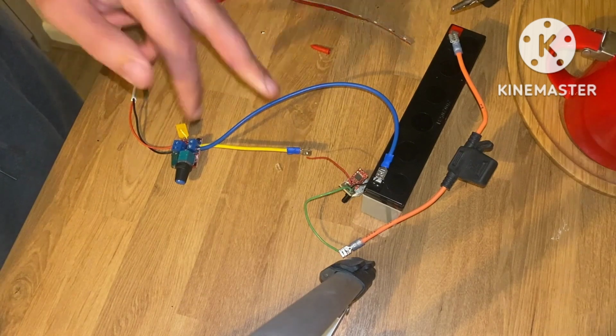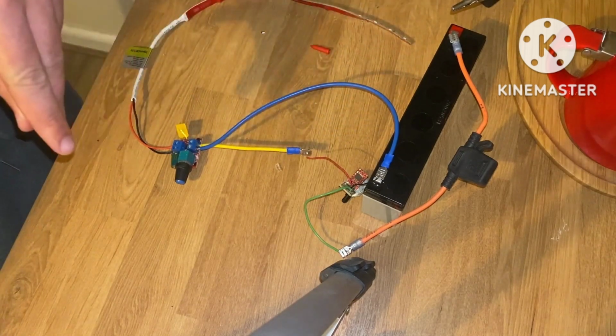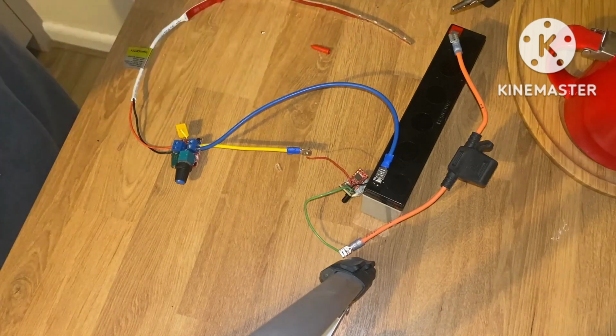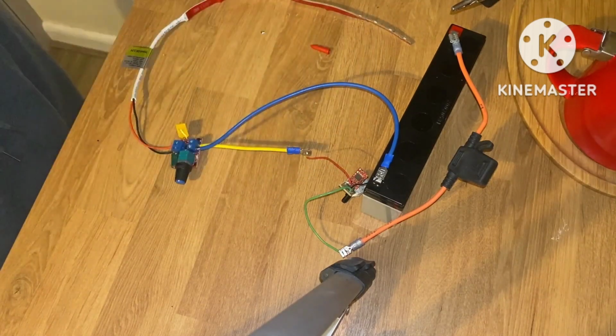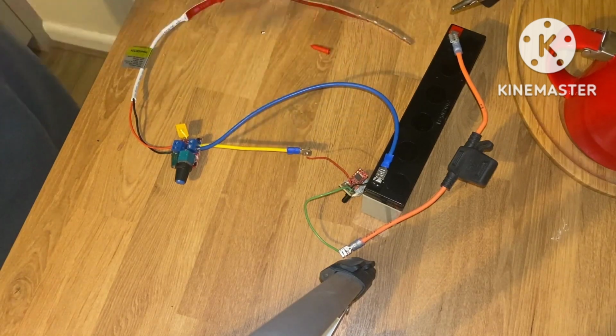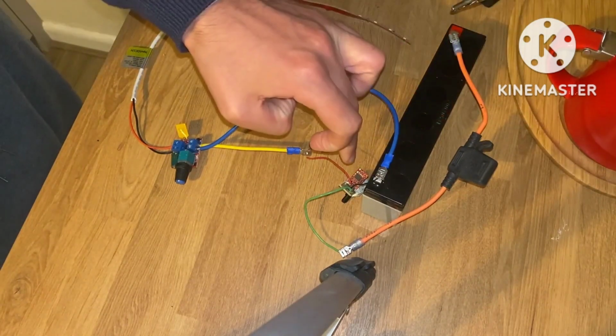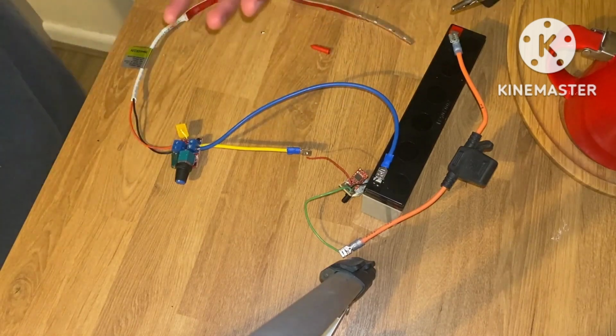And that's the reason why I have that power supply as well, because it just regulates the voltage. I can make sure that the LEDs are seeing the lower side of their voltage, which means they will last longer, which means I don't have to take the model apart regularly to change LEDs out. The longer they last, the easier it is to keep the model going, really. So that's why the power supply is in the way. Just to reiterate, we've got battery, then the power supply, then the PWM generator, and that's the full lighting circuit now.